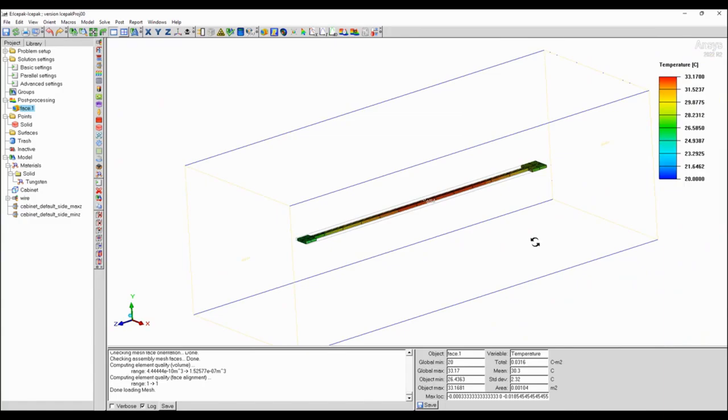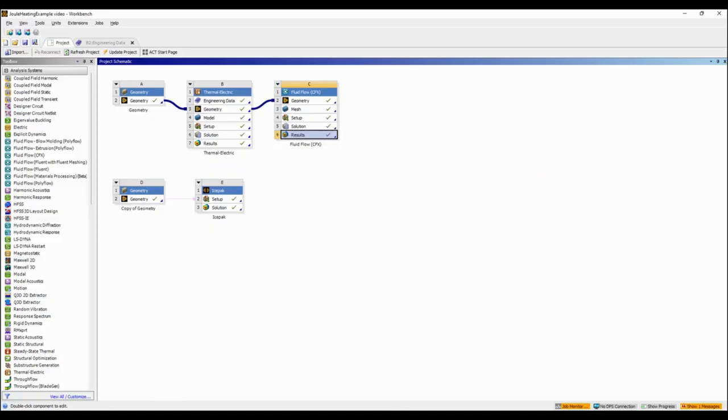But the idea here is I wanted to show you what we do in simulation to do a Joule heating analysis in Ansys Mechanical using conduction-based thermoelectric. We can do in our Ansys CFD product a full detailed CFD analysis that gives you a lot of control for meshing and boundary layer modeling, advanced turbulence models, and for very large electronics cooling applications where you may have hundreds if not thousands of components, Icepak lets you set up these models super fast. So 3 different solutions, all can do Joule heating.